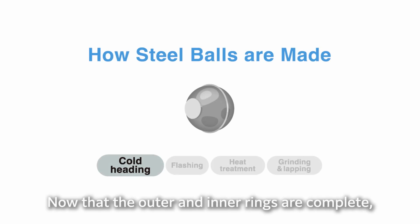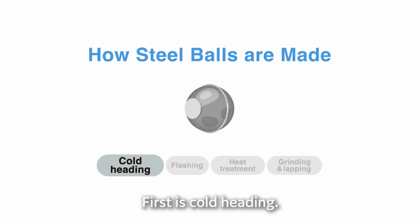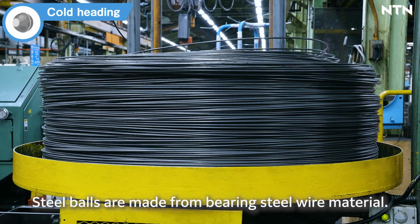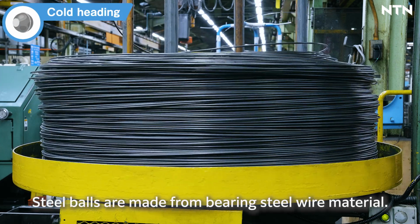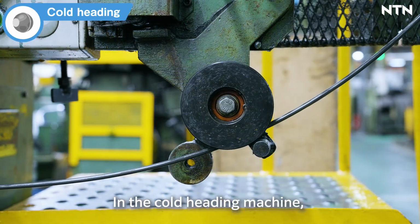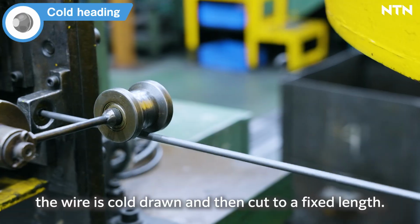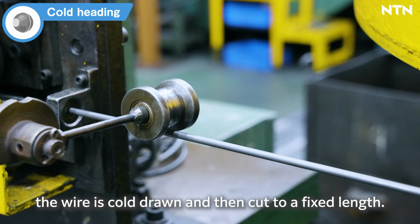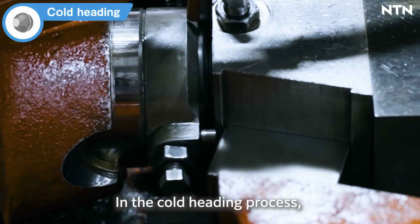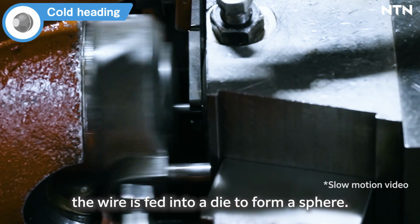Now that the outer and inner rings are complete, let's move on to the steel ball manufacturing process. First is cold heading. Steel balls are made from bearing steel wire material. In the cold heading machine, the wire is cold drawn and then cut to a fixed length. In the cold heading process, the wire is fed into a die to form a sphere.